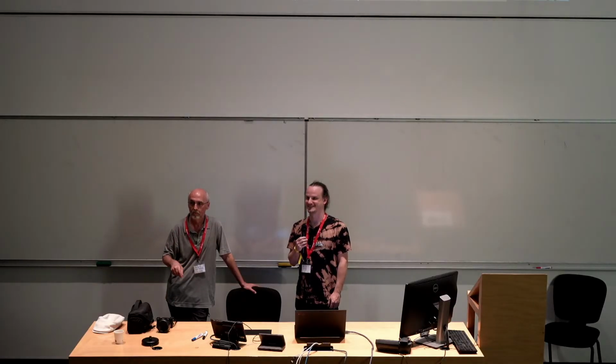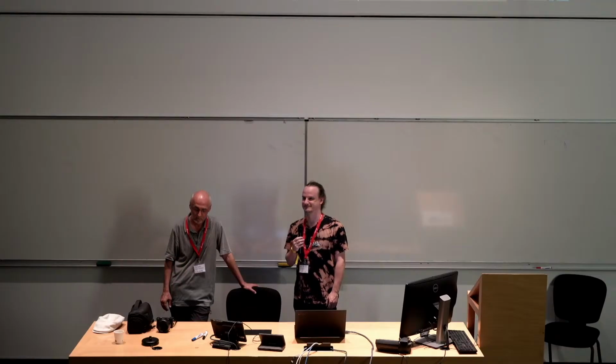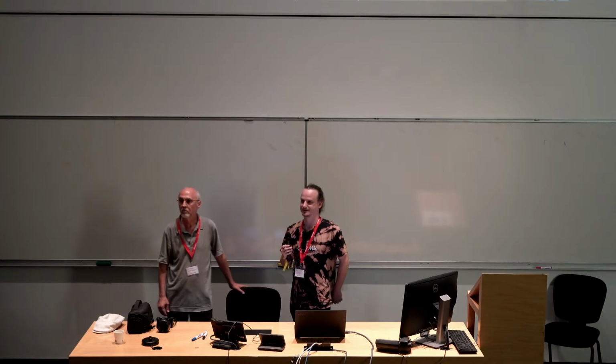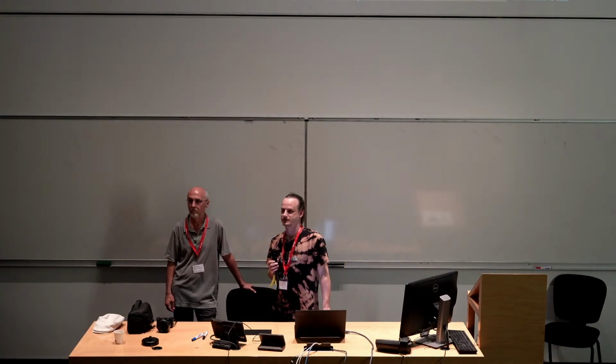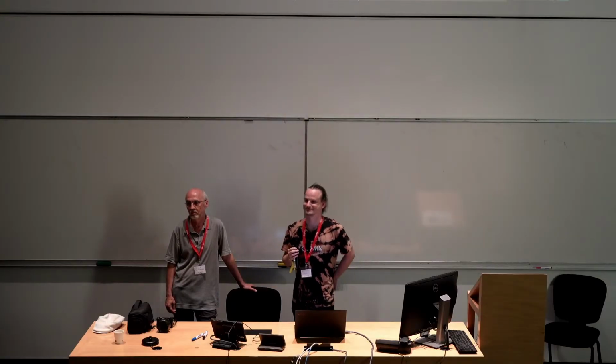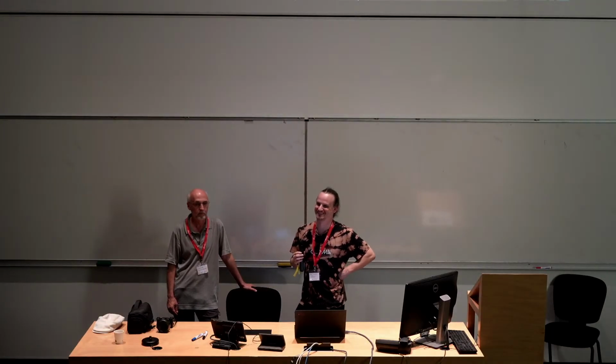Yeah, hi. Thank you very much for this great presentation. I want to point out one thing that was not clear for me, at least from your presentation. That's the latency issue. So the presentation time offset in AVB can be set to up to 2 milliseconds. It's not fixed to 2 milliseconds because for some historical reasons, this is sticking with people's minds.